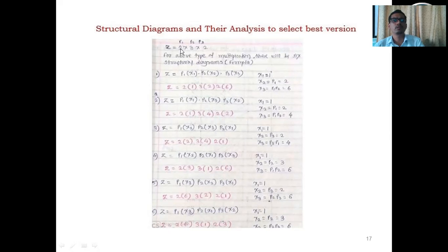So that will be Z = 12. Okay, 2 × 3 = 6, 6 × 2 = 12. So Z = 12 speed steps are there. For that Z = 12, we get the number of structural formulas as 6. The second structural formula is 2, 1, 3, 4 and 2, 2. Similarly, we will get the different structural formulas for the same Z = 12.